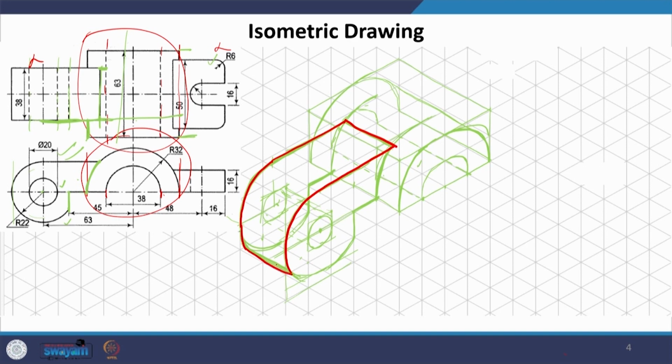The fundamentals of course remain the same, and we will have to darken this part, because no edge can just, this is a different surface. Whenever two surfaces at different inclination or different plane come together, there will be an edge which will be joining them, which is what we will always see and also draw. The rest of the portion can be drawn in dotted,